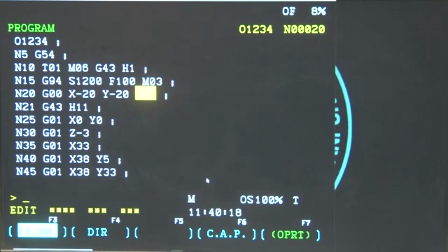If you remember, initially I told you that the difference between the NC or computer numerically controlled machine and the conventional machine is that in the CNC and NC machines we have an individual prime mover or motor along each axis, that is X, Y and Z, which can individually be given movement. Therefore, we can have different kinds of relative movement between the tool and the workpiece to generate various surfaces. That is the basic difference.